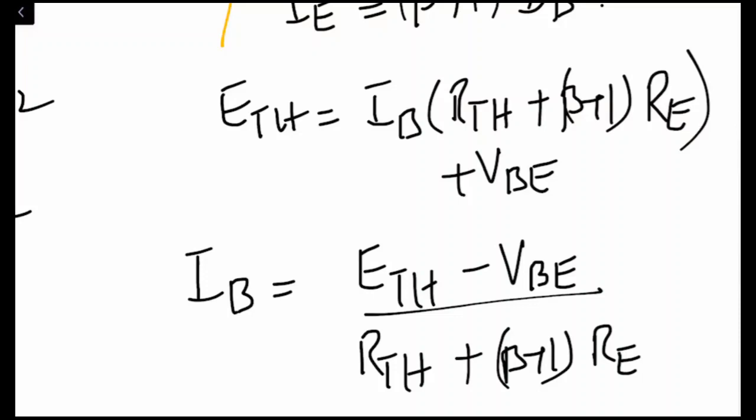So if you see, in this way, if you have a voltage divider circuit and go with the exact method, we will have an equation more or less similar to the biased emitter circuit, with the only difference that in the numerator where we had VCC, the biasing voltage, it is replaced with the Thevenin equivalent voltage, and in the denominator where we had the base resistance, it is replaced with the Thevenin equivalent resistance, right?